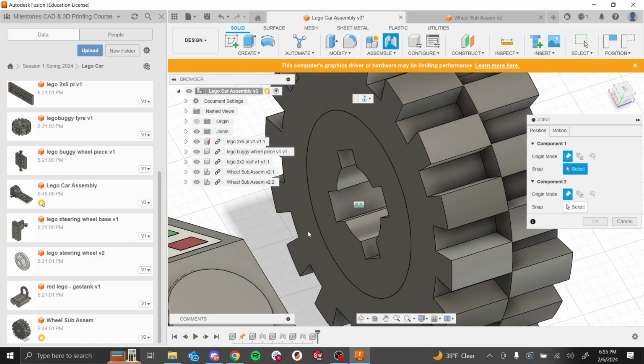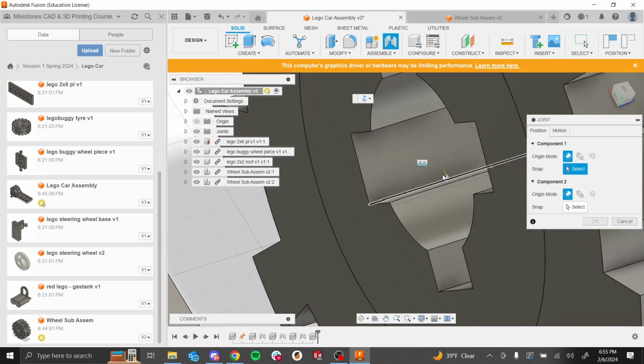If you look closely, on this arc, when I approach the middle of this arc, you'll see this little icon snap to where my cursor is, with the green, red, and blue lines. It's basically showing the origin at which you want to revolve or join your part, right? So we want it to revolve around the center of the circle and not the center of the arc.